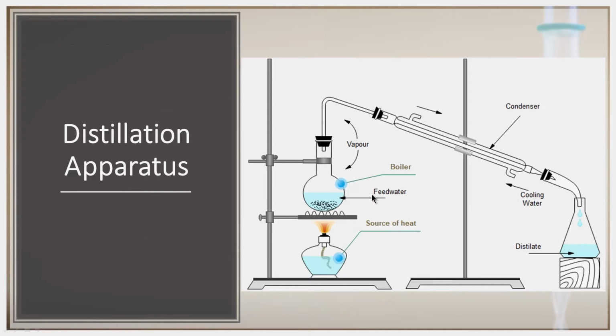An appropriate head space is necessary above the level of feed water, with a condensing surface for refluxing the vapor, thereby returning the non-volatile impurities to the feed water, and a condenser for removing the heat of vaporization, thereby converting the water vapor to liquid distillate.